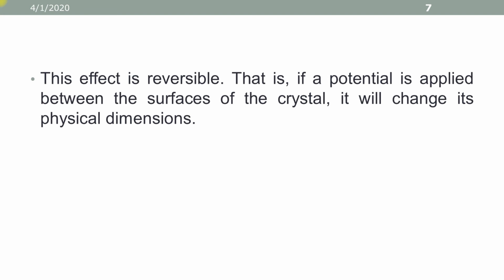First we discussed that when a force is applied, a potential will be generated. Now the reversible effect, which we are not using for calculating force, but you should know the effect. If a potential is applied between the surfaces of the crystal, it will change its physical dimension. So these are the two properties. We will use the first property: when force is applied on the piezoelectric material, it will generate an electric potential, and the electric potential will be proportional to the force. From this we can calculate the pressure.